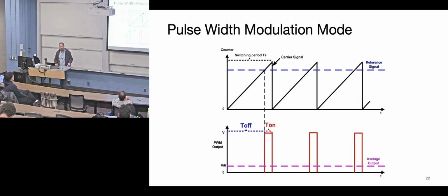Okay. So really bright LEDs are in this range too, where the average current consumption that they can handle can be, say, 10 milliwatts or something like that. But you can actually pulse them to 50 milliwatts if the time is short enough. So if your duty cycle is small, you can make little bright pulses. For humans, that doesn't matter, but maybe your application needs a strobe or something. All right, any other timer questions?